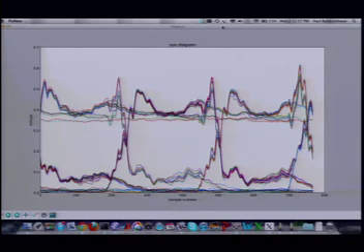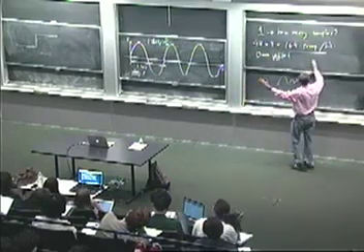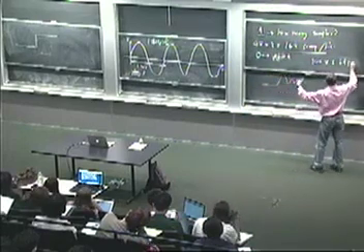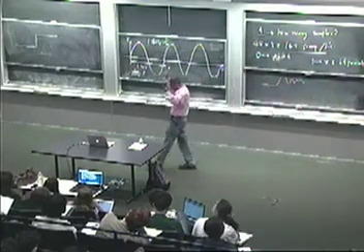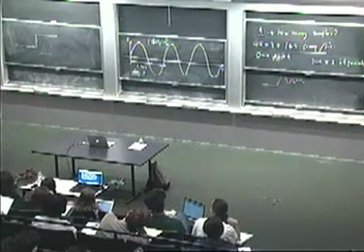The output of the demodulation is a set of voltage values. What you do is you look at 3-bit periods. In other words, you look at a number of samples that corresponds to 3-bit periods. So for example, if I pick 144 samples per bit, I take 144 and multiply that by 3-bit periods, and I look at that many samples. So for every 3-bit periods, I take all the samples and I plot them.